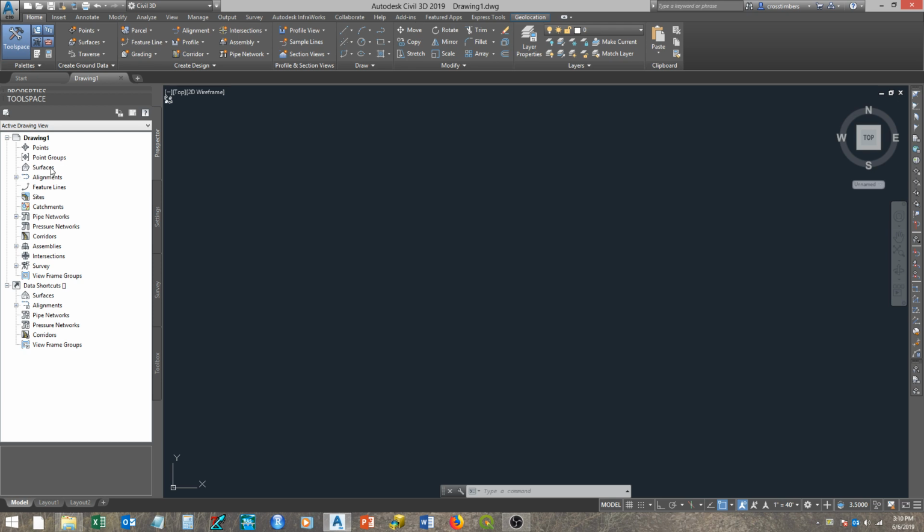Over here on the left there's a surfaces icon, and we want to create a surface, but for later purposes there's a reason we do it a certain way. We right click on here, and there are three main options: create a generic surface, create a surface from a DEM, which we do have, and create a surface from a TIN, which we don't have.